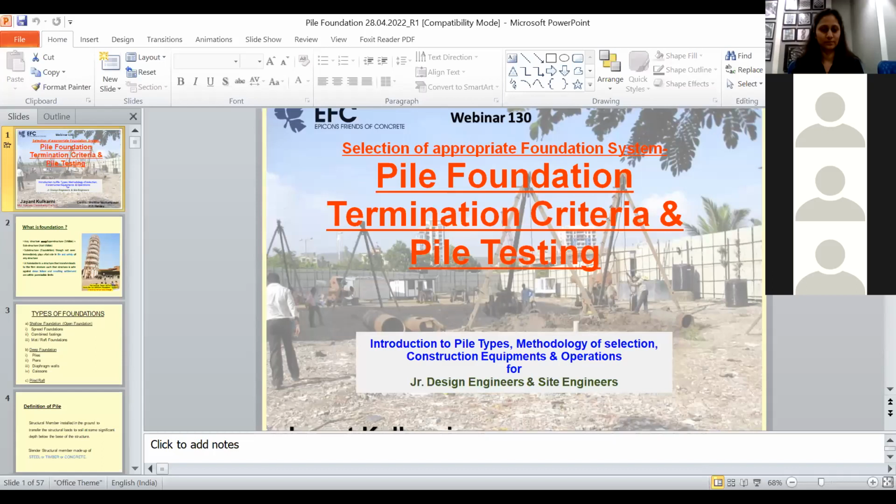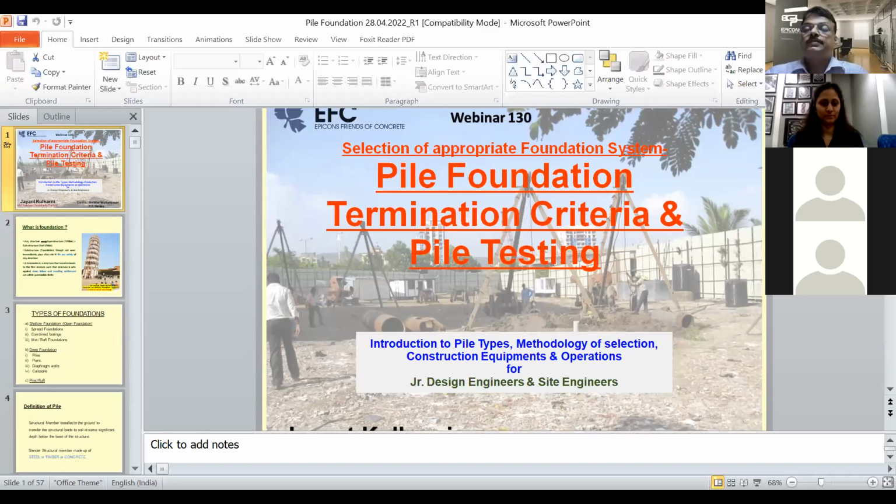A foundation is a structure that transfers load to the firm stratum such that the structure is safe against shear failure and resulting settlements are within permissible limit. Not having done that, it is likely that the structure may sink or may tilt, and you may not be as lucky as the constructor of the Pisa Tower. That tower became world famous because of sinking.